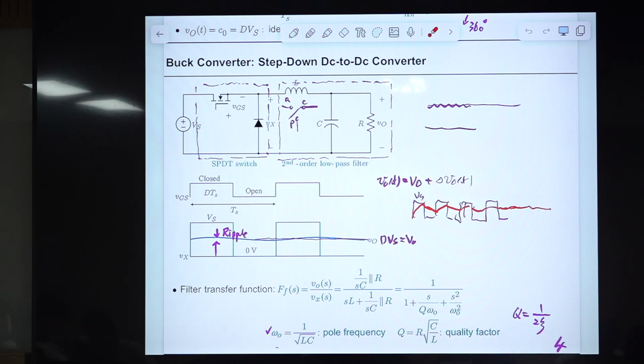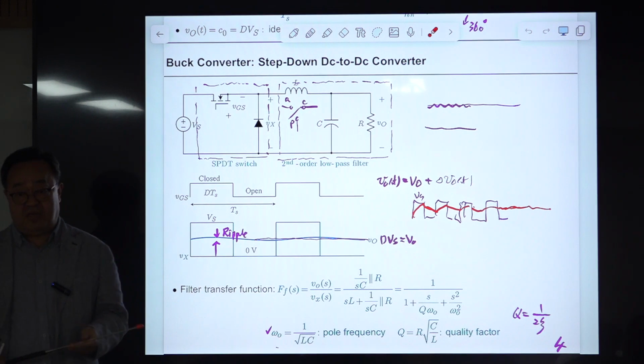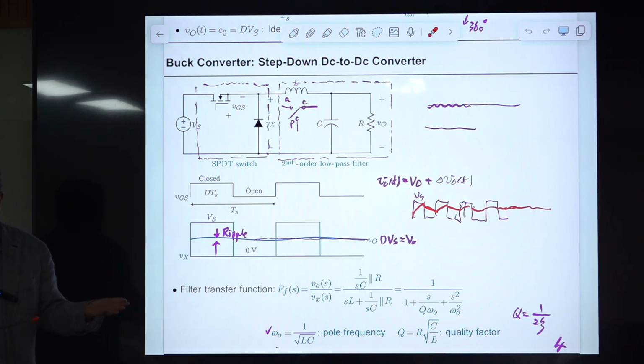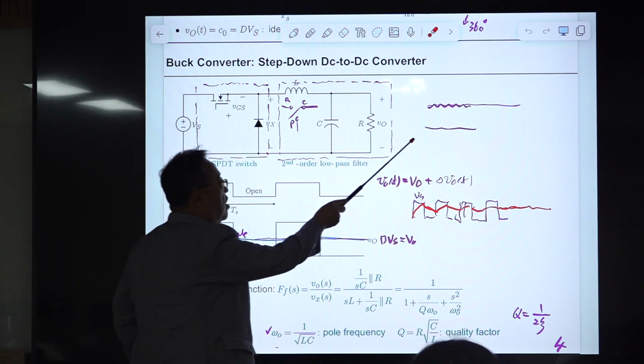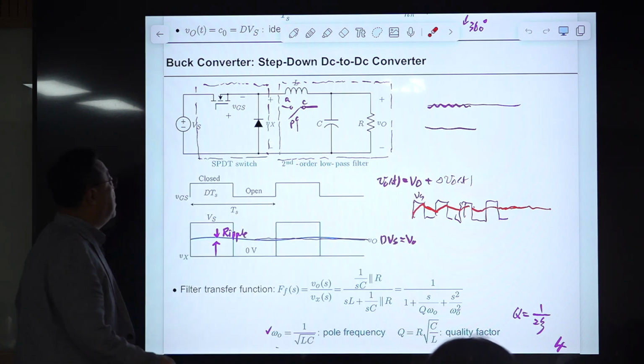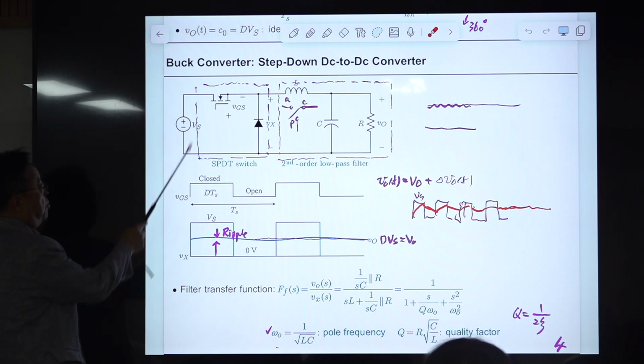I'd like to go back several pages. We covered this, and it explains the structure of the buck converter. Buck sometimes means step down. In old English, buck means stepping down something; the voltage-transformer sense is a term borrowed from electrical engineering. So buck means stepping down voltage and generating another level of voltage. We went through the ideal DC to DC step down operation, and this is the practical one.